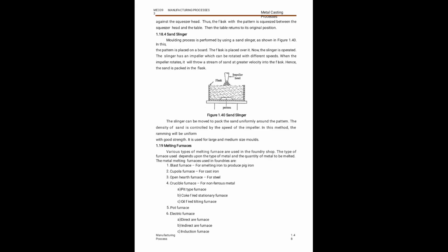The slinger can be moved to pack the sand uniformly around the pattern. The density of the sand is controlled by the speed of the impeller. In this method, the ramming will be uniform.